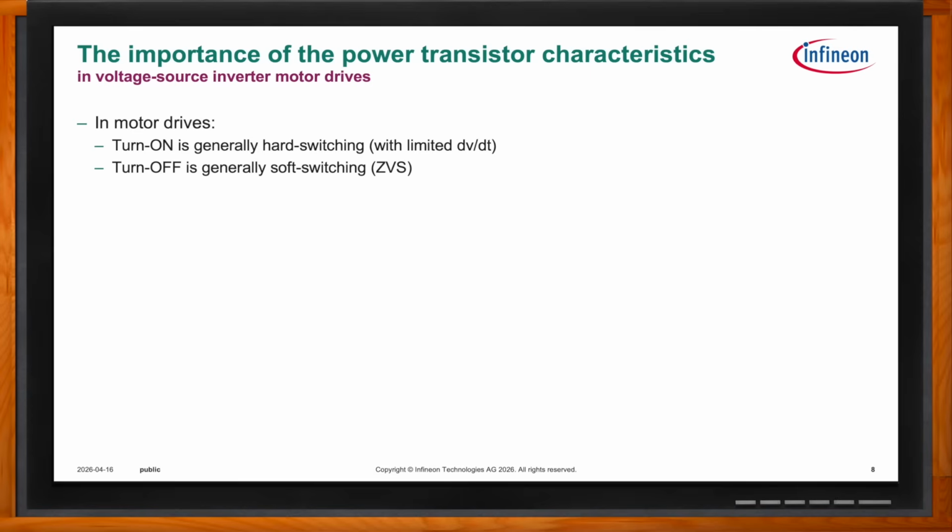And in that case, the DVDT is limited sometimes as low as like 5 volts per nanosecond, which sounds fast, but with these modern fast switching transistors, it's possible to achieve 10 times higher than that. The problem is that in high voltage machines like that, the fast transients can cause corona breakdown or partial discharge, which leads to degradation of the insulation system.